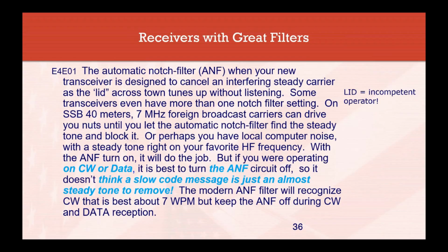Generally, a modern filter will recognize CW at about 7 words per minute. So keep the automatic notch filter off during CW or data. Don't let it get in your way. Don't risk it, basically. It's a good thing on voice, but not so much for CW and data.